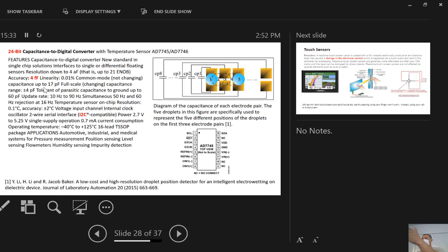And since the breadboard has all these metal pins and all the plastic materials on the board, if you measure these 2 pins on the breadboard, usually you are getting picofarads level. That's called parasitic capacitance, in between all the holes on the breadboard, usually tens of picofarads.